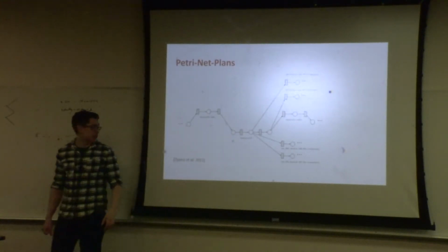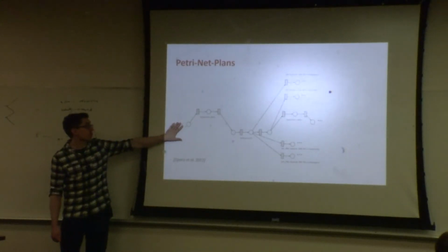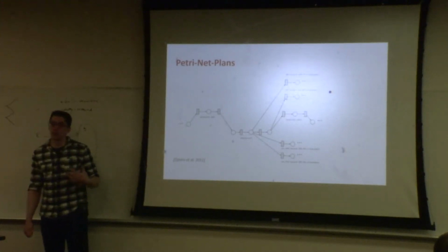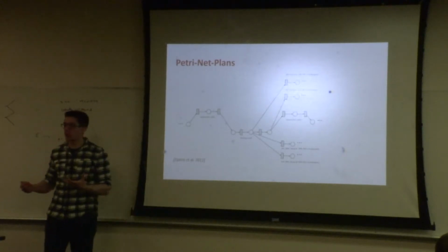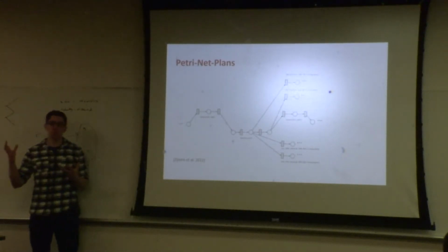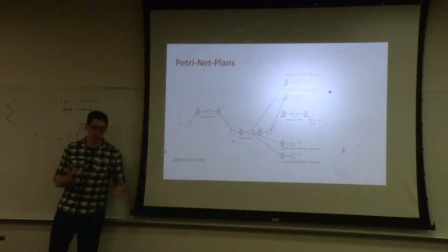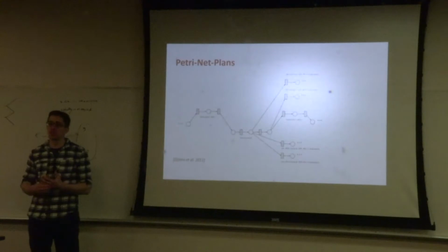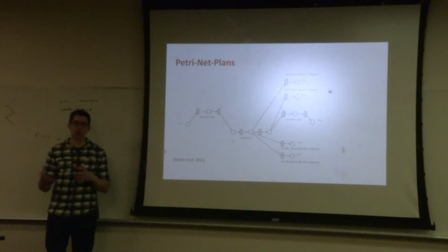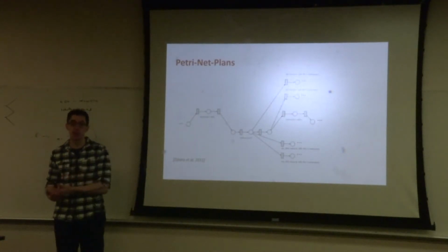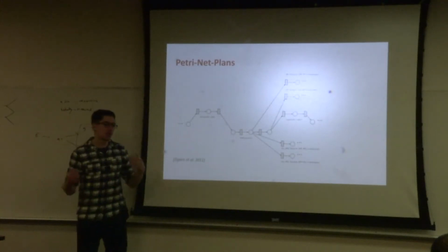And Luca Iocchi, who gave the talk yesterday, worked on this with execution rules, where you can generate the PetriNet corresponding to the plan produced by your planner, and then combine it with some small execution rules that were written by hand, such as if this action takes longer than 5 times its duration, then return to waypoint 0. So some of those, how to recover the state, could be hand coded and then compiled into the plan to produce a more complex PetriNet that you can then just execute.